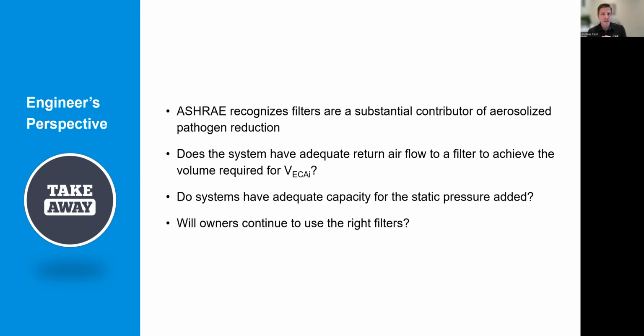The pathogen itself is actually very, very small. But the assumption is that the pathogen is wrapped in mucus or in water droplets, so you get the larger sizes, which is why you rate filters to a slightly higher result than would normally have been the case for these small particles. To give you an idea, that's the justification that ASHRAE put together for these filters.